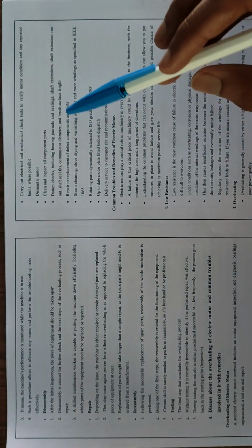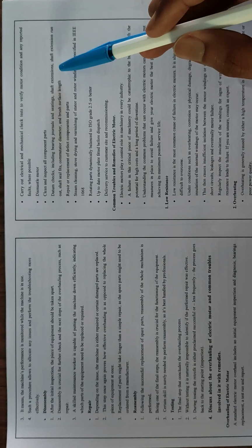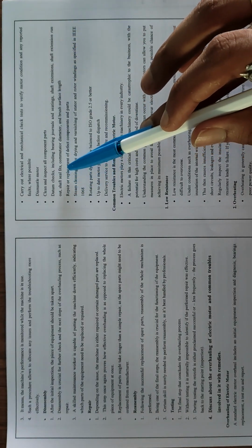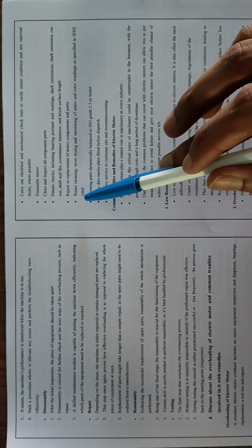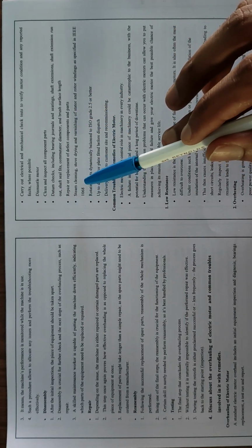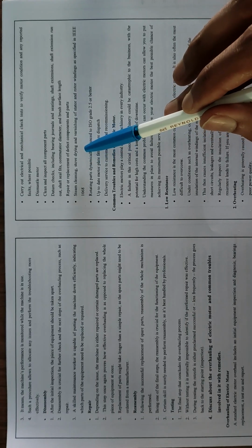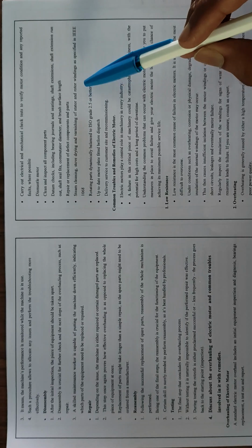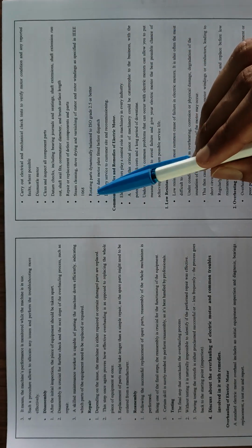Datum checks including bearings, journals and seatings, shaft expansion, shaft extension, run out, shaft seal fits, commutator diameter and brush surface length, repair or replacement of defect components and parts, steam cleaning, stove drying and varnishing of stator and rotor windings as specified by IEEE 1068.